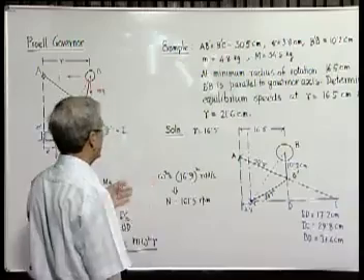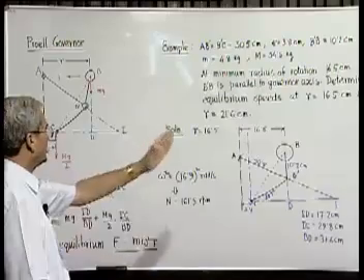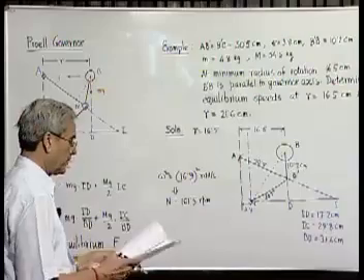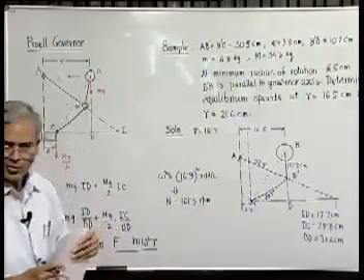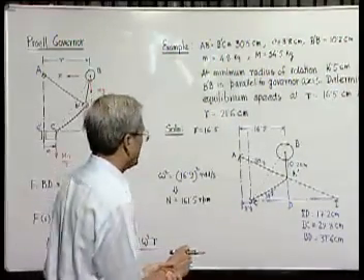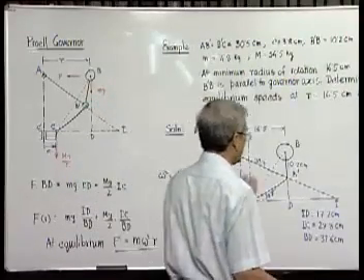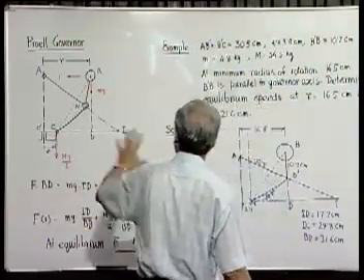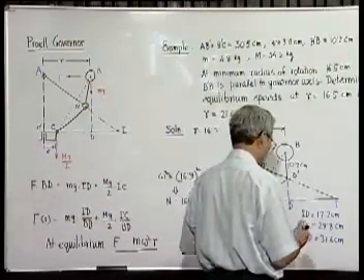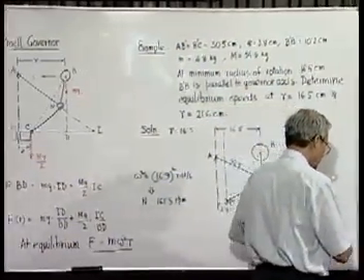So, therefore, we can find out the equilibrium speed for various radii at which the sphere can rotate in a stable manner. I think this will be enough for our discussion of gravity controlled centrifugal governors. Now, I think next we will go for further improvements. You can see that we have certain disadvantages if we depend on gravity for all our controlling operations. To have large force, we have to have a large mass, it will make the system heavy and so on.